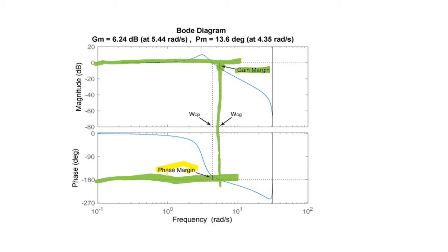As for our phase margin here, we need to look at it from the 0 dB here until it crosses the magnitude plot. From here we go down until you cross over at the phase plot, and then from that point to 180 here, it is actually our phase margin. That is how we find the gain margin and the phase margin of the system.